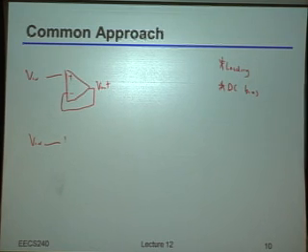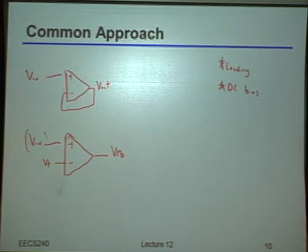There we go. You said put a really big inductor in, right? Okay, so just to be clear where we would put that inductor in, let me give a little bit of the setup. So let's say that I want to measure the feedback out over there, and I want to apply the v-test right there. Okay, so when I said v in here, really that's going to be, incrementally speaking, ground. Okay? So how would I place a really big inductor to allow me to apply v-test on one side and measure v-feedback on the other? Where should it be connected? Like, what should be connected between?